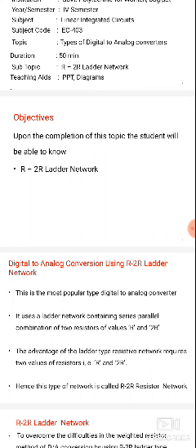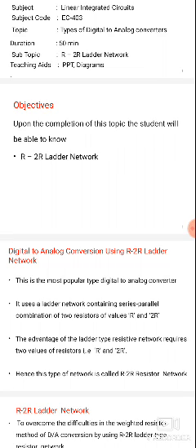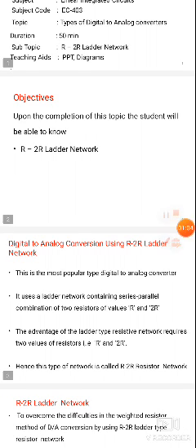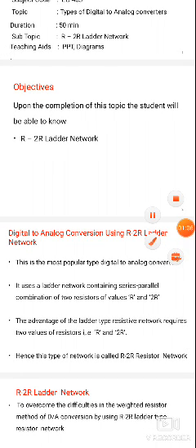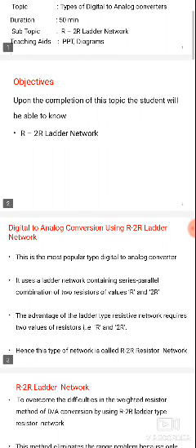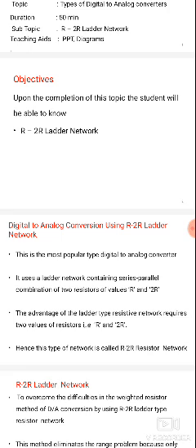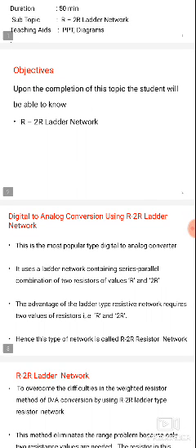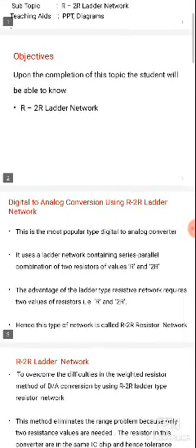For converting from digital to analog, we have two methods. The first one is the binary weighted resistor and the second one is the R-2R ladder DAC. In the binary weighted resistor type, as the name itself says, it contains binary values. The binary values depend on the weights of the resistors, that is R, 2R, 4R, 8R. These were completed in the previous class.